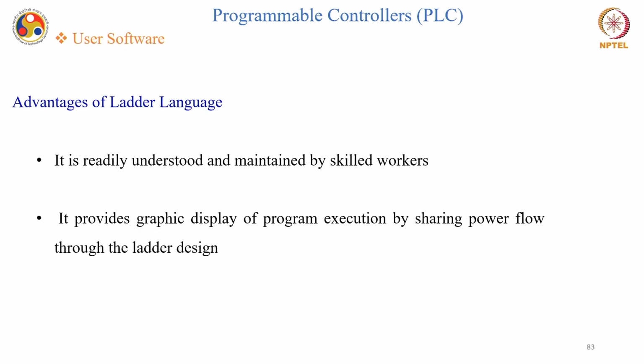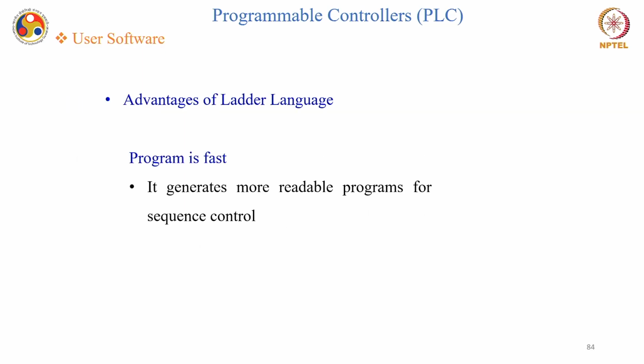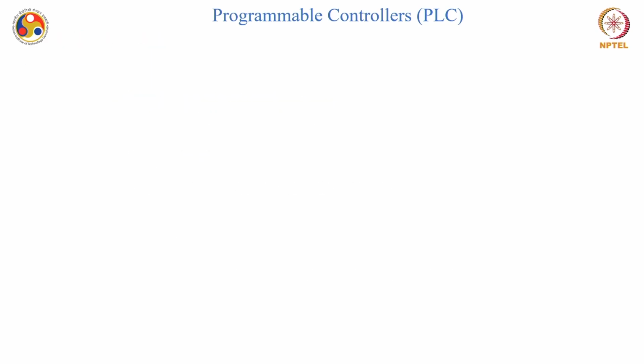Now, there are enormous advantages provided by the ladder language, and that's why it is more preferred in PLCs. It is readily understood and maintained by any skilled worker. It provides a graphical display of program execution by showing power flow through the ladder design. The program is also fast, and it generates a more readable program for sequential control.